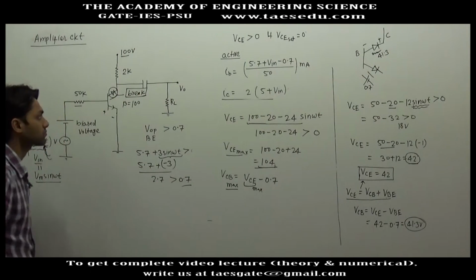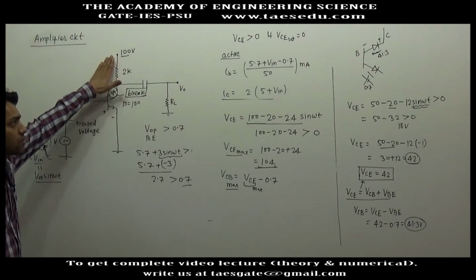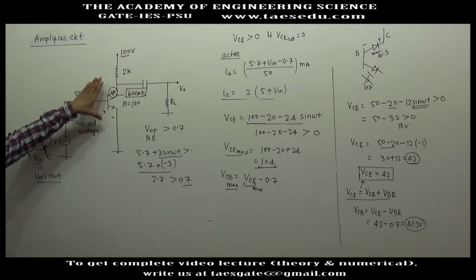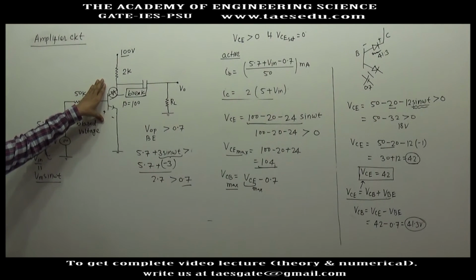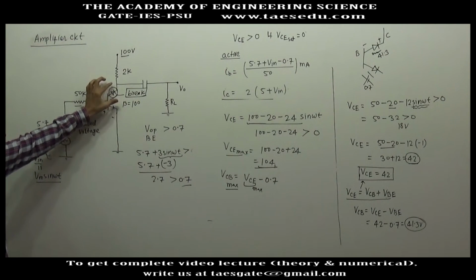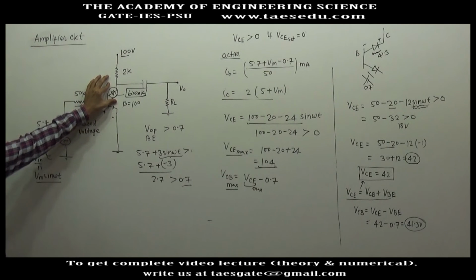So we cannot increase this voltage. Although if you increase this voltage also, you will prevent this transistor from going to the saturation region, the reverse bias voltage across this junction will increase and this junction may break down.